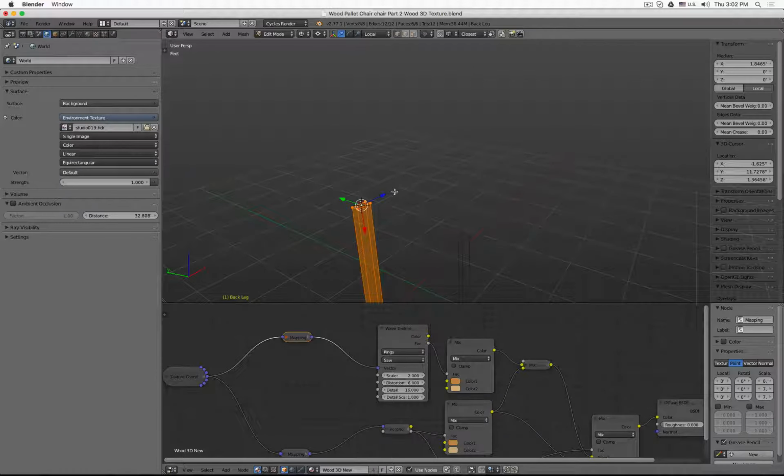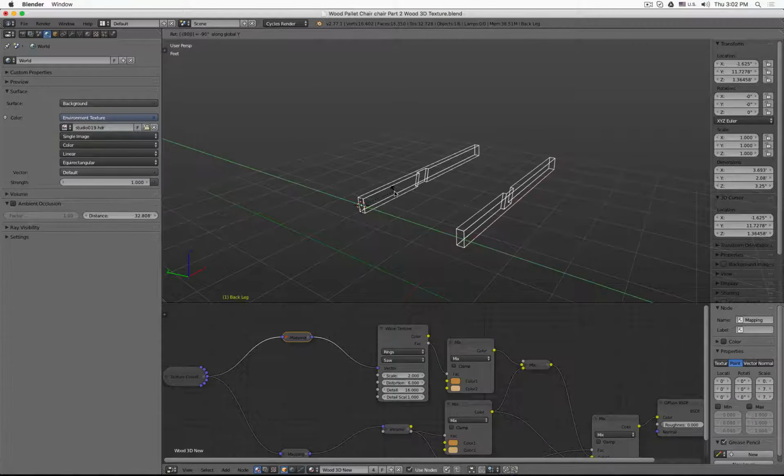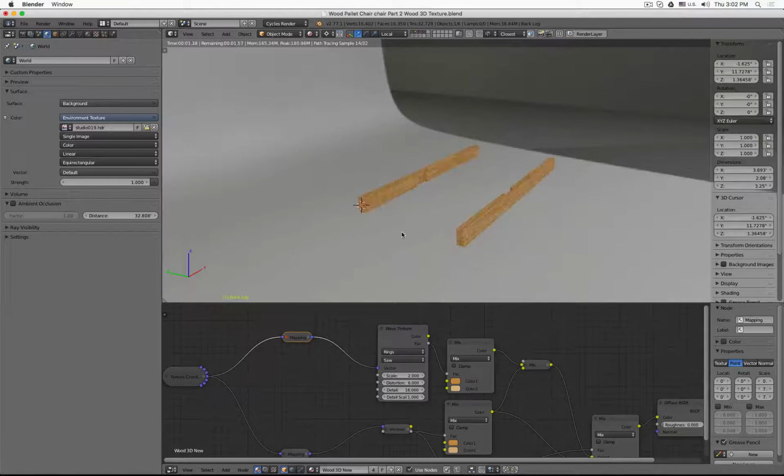Okay, leave edit mode, and then in object mode, R, Y, the opposite 90. Before I rotated Y positive 90, so this time I need to rotate negative 90. Press enter. You also see in local space now how the x-axis flows again along the object, and that is correct.